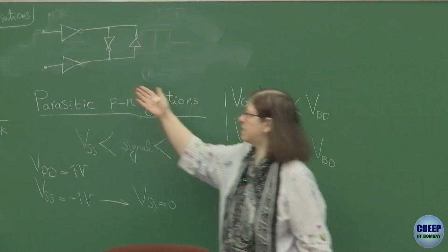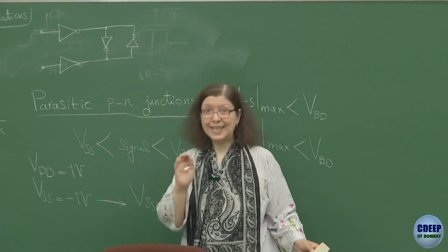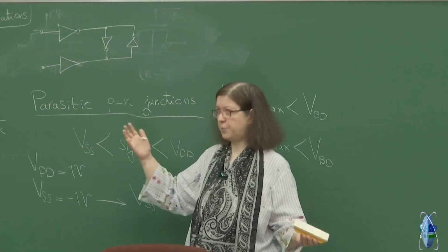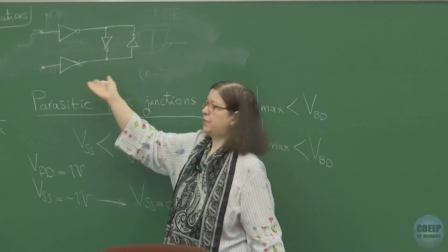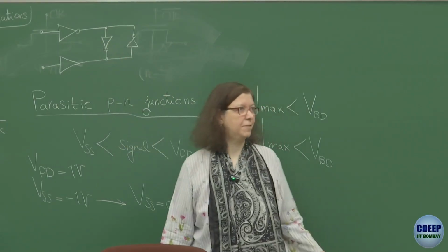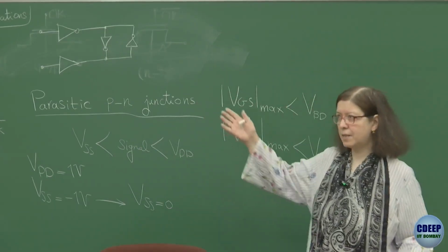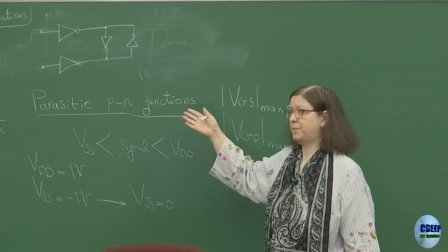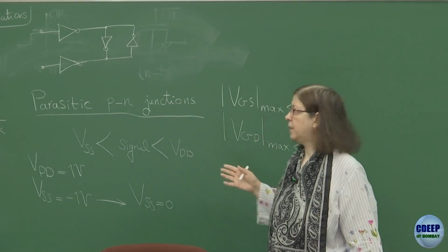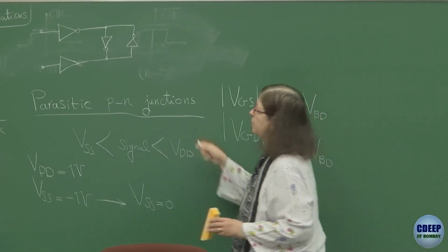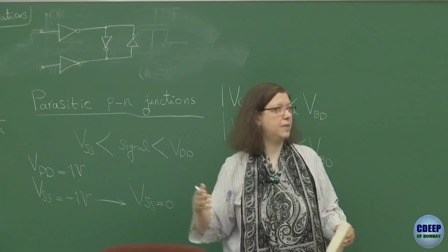All these inverters are like buffers. At the end of the day, you want to drive the clock gate of all switches, therefore you need buffers. So you load each one of them with the other one. You cannot directly short them, so you invert them and short them. These techniques are used in SERDES systems, which are dealing with gigabit per second operation. And they continue even with the chain to make it better and better, so multiple stages.